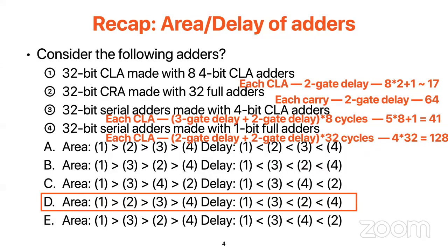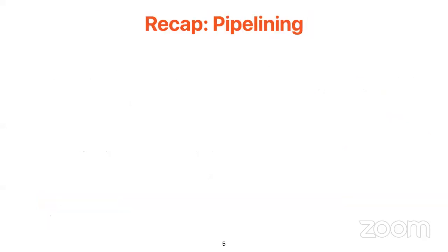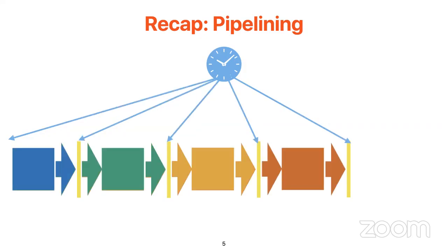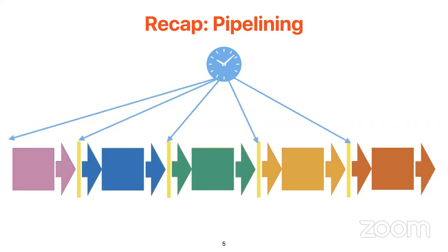However, a very important technique that is widely used in modern digital circuit design is the pipelining idea. The basic idea of pipelining is that each part of the hardware component only performs part of the job for an operation, and then uses pipeline registers to buffer the intermediate results and propagate them as the input of the next stage.